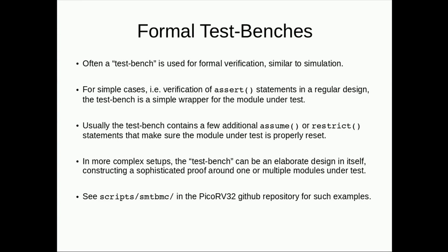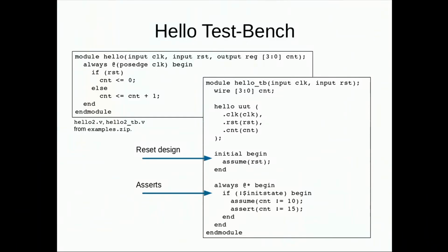we just add some external restrictions or assumptions for stuff like, well, reset should be low in the first cycle, things like that. But other than that, we leave a lot of free room for the verification tool to actually explore different parts and see if, using the thing in the formal test bench, it can reach an invalid state.